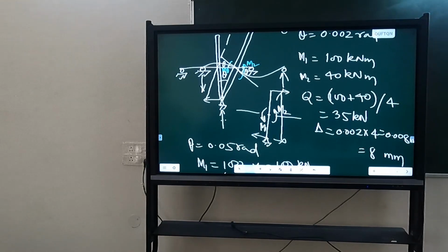See, you have to consider that beam which is reaching its ultimate displacement first. So which one will reach ultimate displacement first? Beam 1. Yes. Why? Because ductility ratio is less. But it is yielding also earlier.